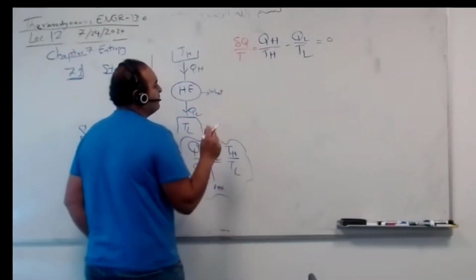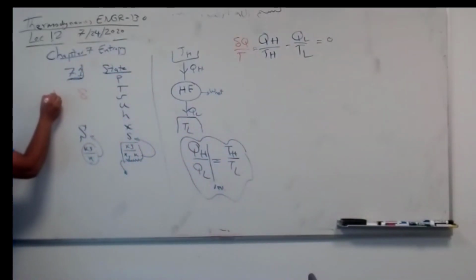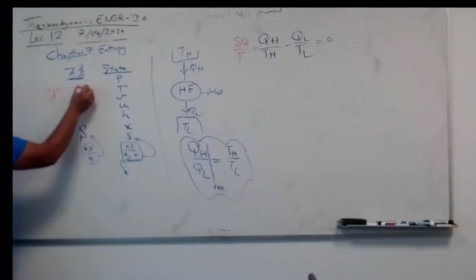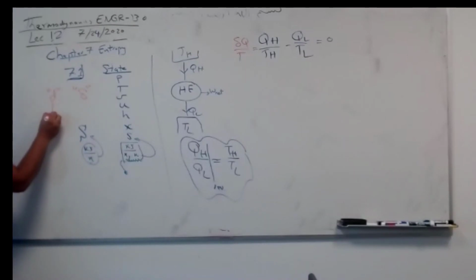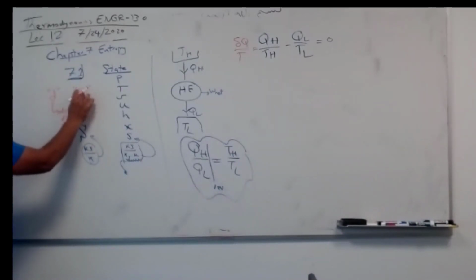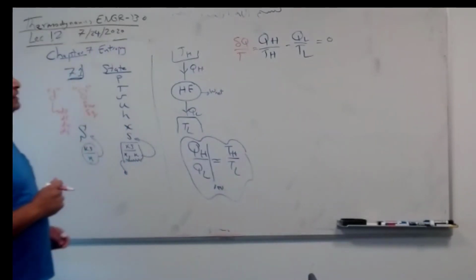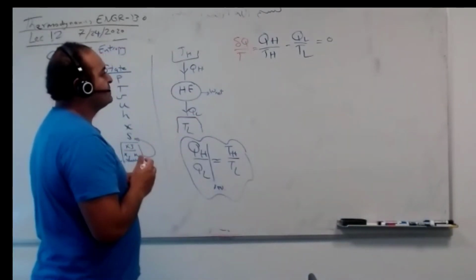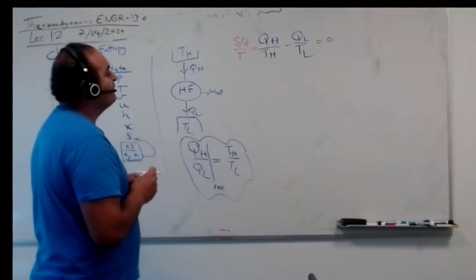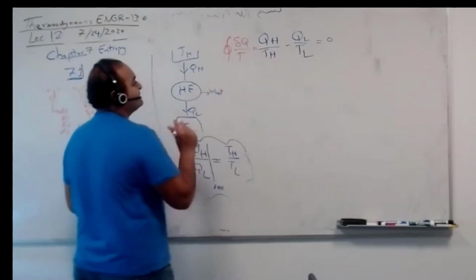As we talked before, we have two things, we have delta and we have d. One is called exact, the other inexact. If it's a property, it's d, like dP, dT, dV, ds, for example. But if it's not associated with a state, it's delta, like delta work, delta Q per unit mass. So delta Q, uppercase or lowercase, absolute Q or per unit mass, over T is equal to this. This is the integration of that. This is the definition mathematically.